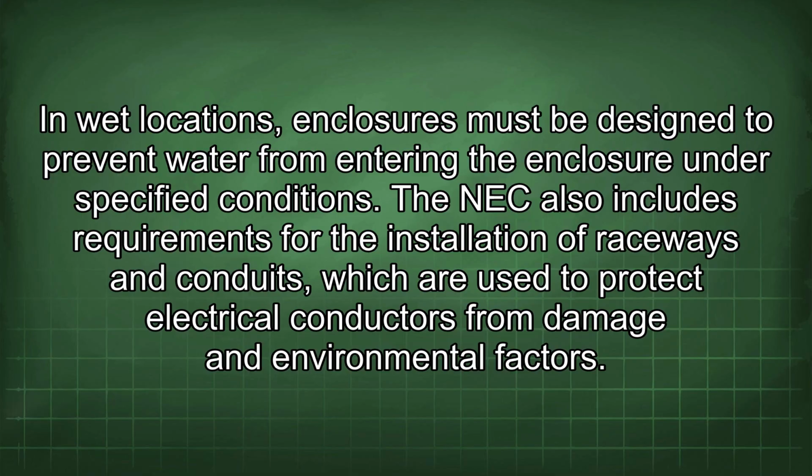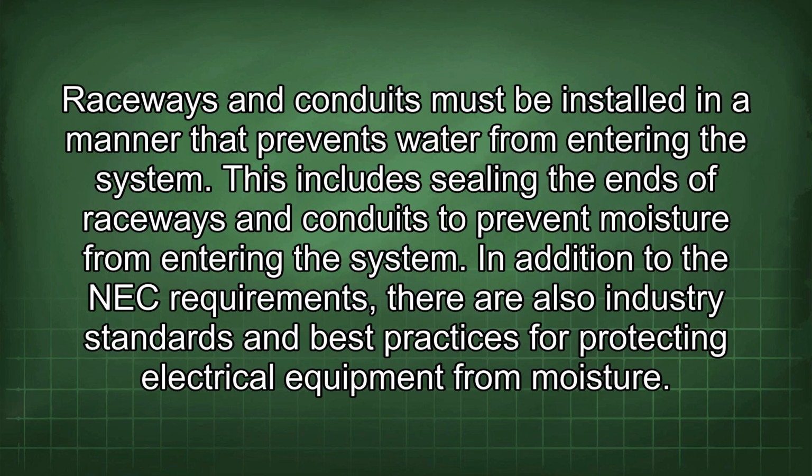The NEC also includes requirements for the installation of raceways and conduits, which are used to protect electrical conductors from damage and environmental factors. Raceways and conduits must be installed in a manner that prevents water from entering the system. This includes sealing the ends of raceways and conduits to prevent moisture from entering the system.